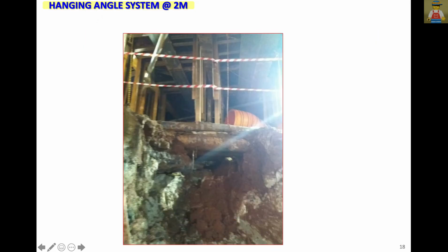And the next one, number 2, is ground to 4 meter depth, between second and third layer excavation time. Above, whatever you can reach at about 1.5 to 2 meter depth, we support first. But if those utilities are deeper than that level, they can be exposed after the first layer strut, during second layer excavation. So during second layer excavation time, we have to use manual as well to expose every 2 meters and extend down the angle to support. Then it can go down for the third layer excavation.